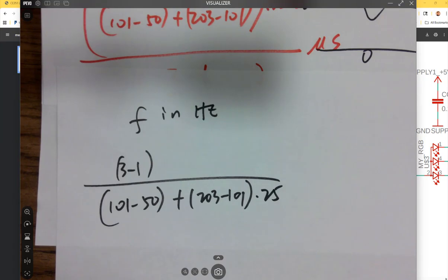Will this work? No, it won't work because it's not an integer, so you cannot use the integer. We all use integers as the preferred data type for our microcontrollers because floating point numbers are fractional numbers and consume a lot of computation resources. So don't try to use floating point numbers for 8-bit microcontrollers.